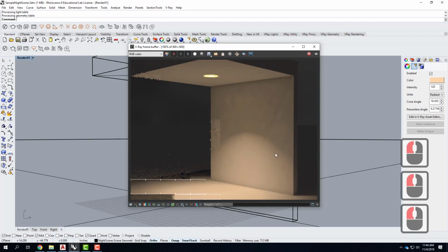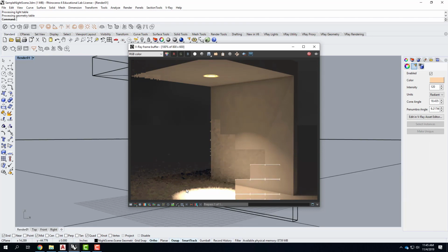And instead of having the nice arc, I've focused the beam of light so that it's now very intense, more of a spotlight down onto the floor, because the geometry of the V-Ray light has changed. So I've shrunk that diameter down, kept the height the same. The relationship of the diameter or the radius, whatever you want to refer to, and the height controls what's happening with the spotlight. So you can see there that it's shining directly down on the floor. I'm getting no fall on the wall itself. There's still ambient reflected light from that spot, but it's acting much more like a true spotlight would.